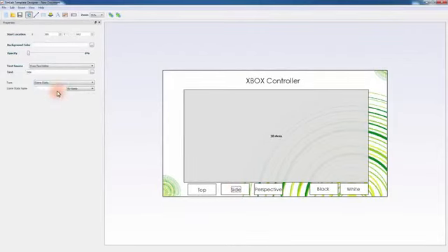In the Animation tab, set the rate of displaying animation frames in the FPS field and determine the playing mode of the animation. In the Advanced tab, you have the option to run a JavaScript or a 3D JavaScript with the PDF file. Other options you have in this page are to disable measurements, preserve image resolution in full screen, and set which parameters to export along with the PDF document.